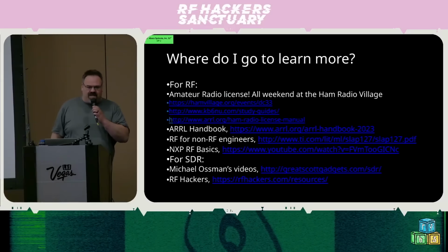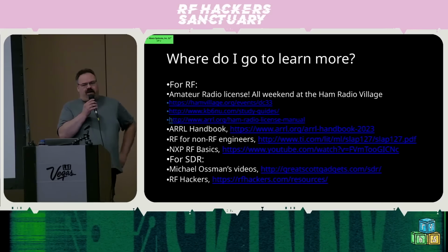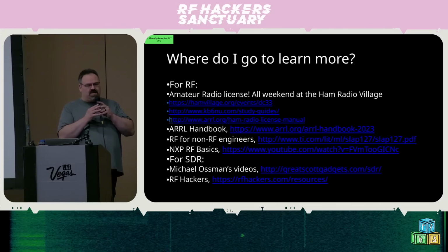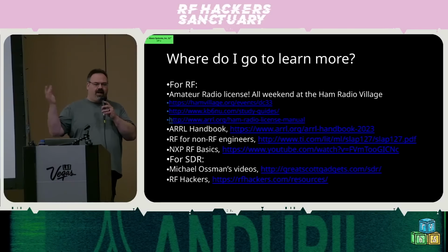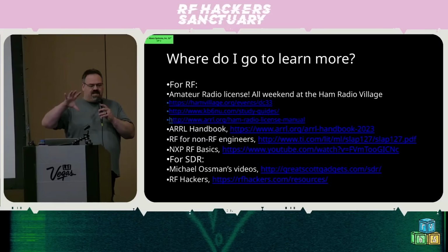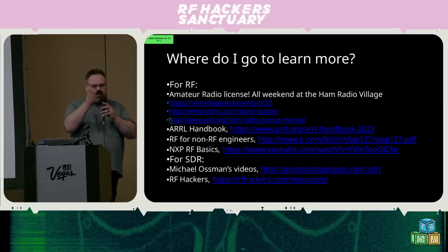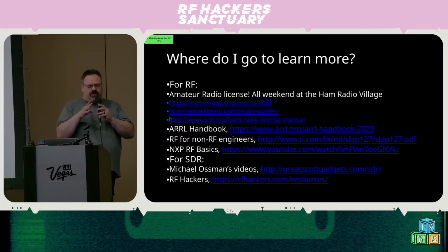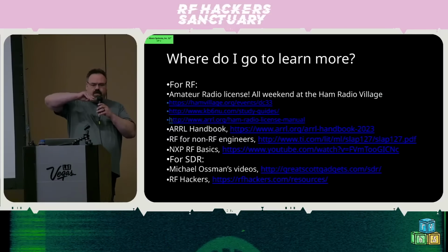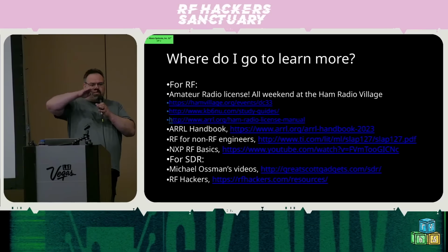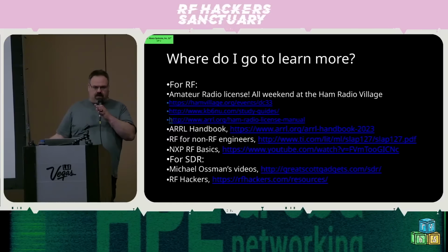Oh, yes, bit depth. So, let's take CD audio, which is a 44 kilohertz, 16-bit file or rate. Those 16 bits mean that for every sample point, you have 65,536 potential values to represent where the wave is at that point in that signal.